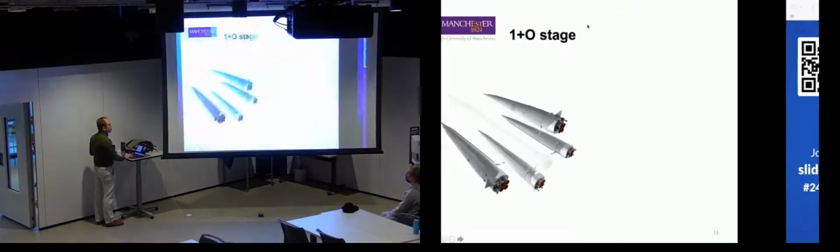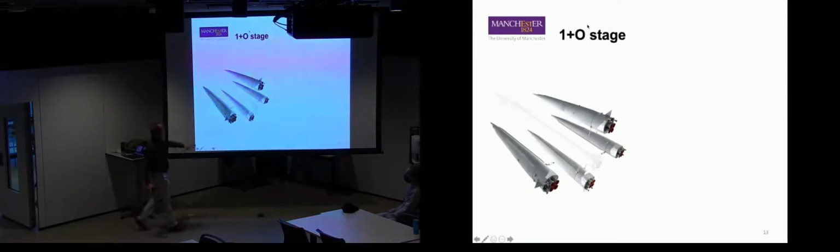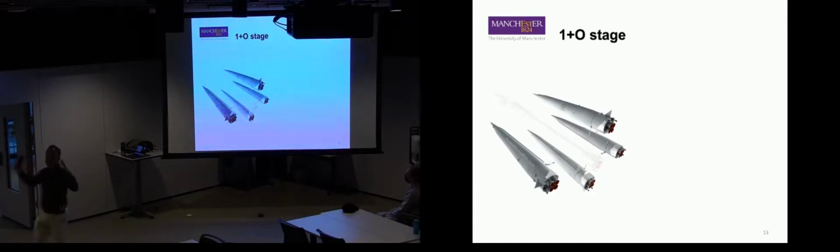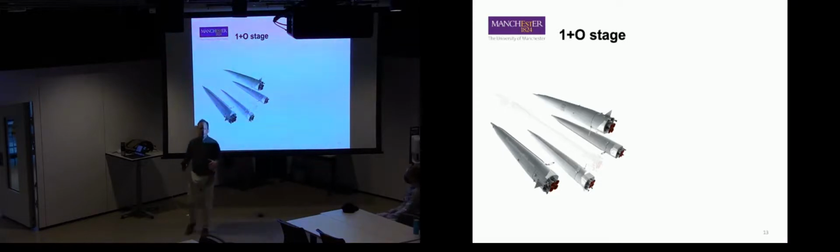And the R7's an interesting one, Soyuz. All of these engines are actually the same. They don't have a different nozzle, but you could put a different nozzle. I don't know how many of you look at what Soyuz looks like when it lifts off. It's in a cradle that opens up. All of that is basically held on by gravity and thrust. There are little motors to improve separation, but when these engines burn out, shut off, it just naturally separates. You hold the rocket on the pad by that, so everything holds together, and then the thrust lifts it up.